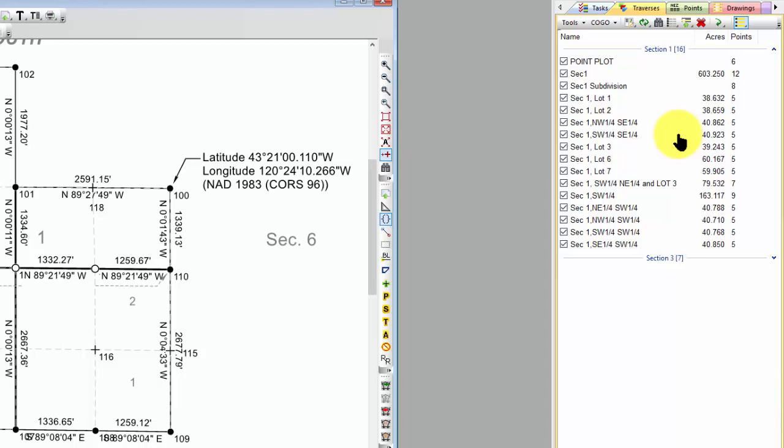So even though I know I'm using a state plane projection to do all the computations, I don't even want to see a grid area down on that projected grid. I want to assume that everything I'm dealing with is ground areas, just like I'm dealing with ground distances. And that's really, really important.